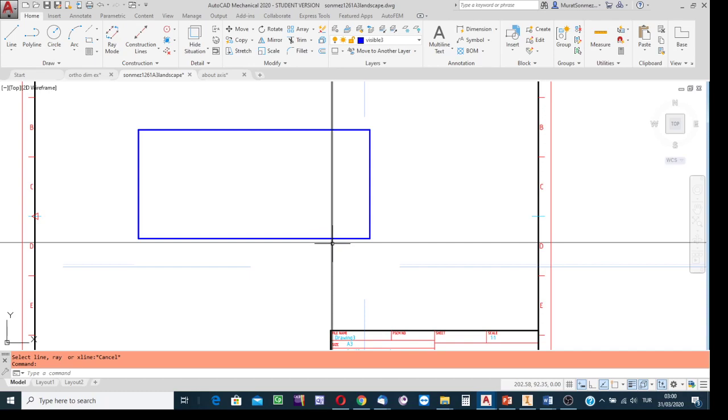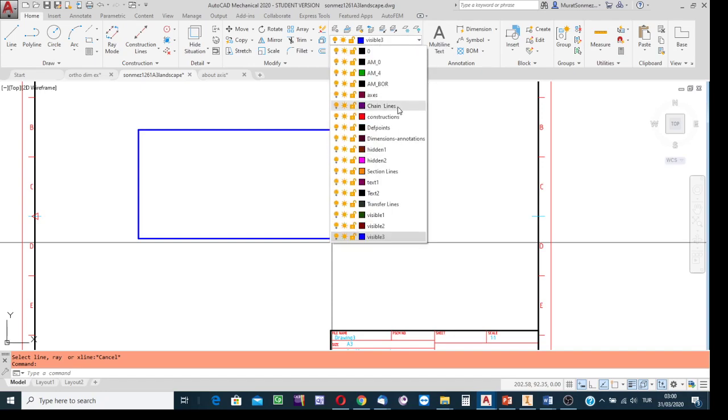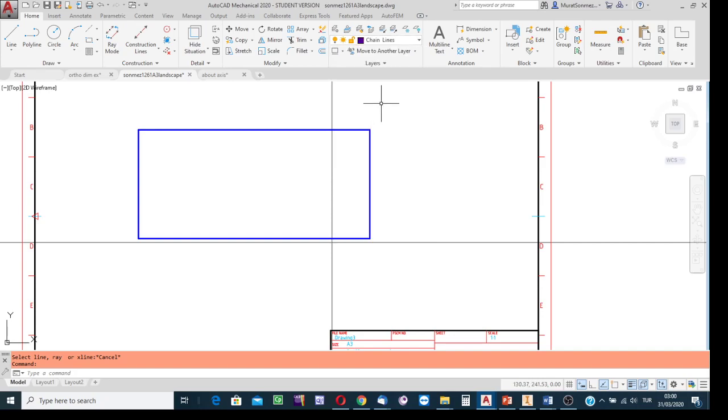Yes, creating this and that. I precisely located the starting point of the chain line. It also corresponds to the starting boundary of the portion of the surface. In this example, it is the bottom side surface for which we have a technical note. Okay, and then select the chain line layer: drop down the list of the layers and click on the chain line option. Select the page and then start the line drawing process. Click on the piece of line creation button.